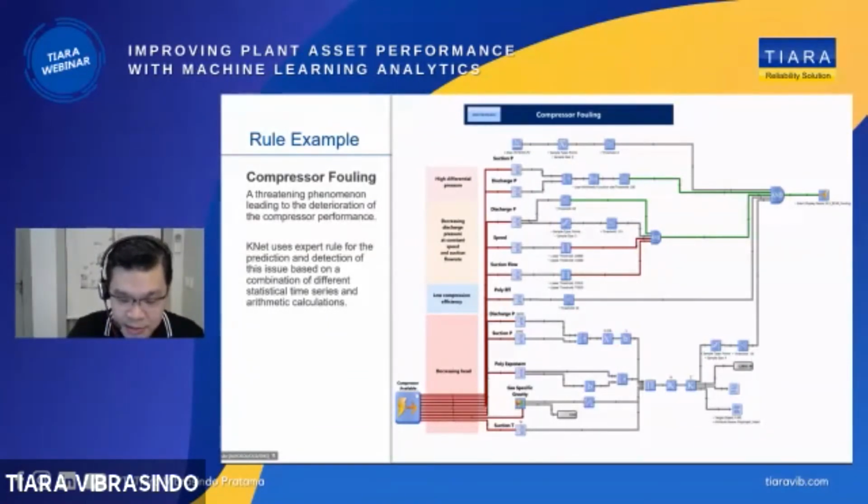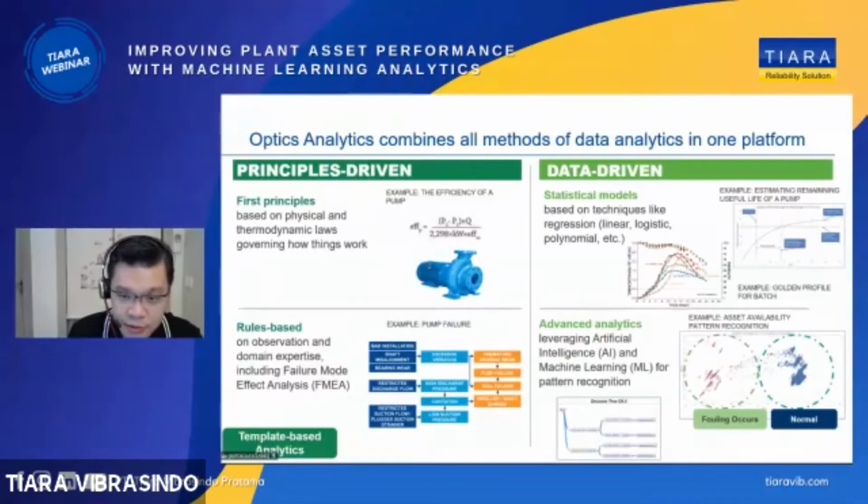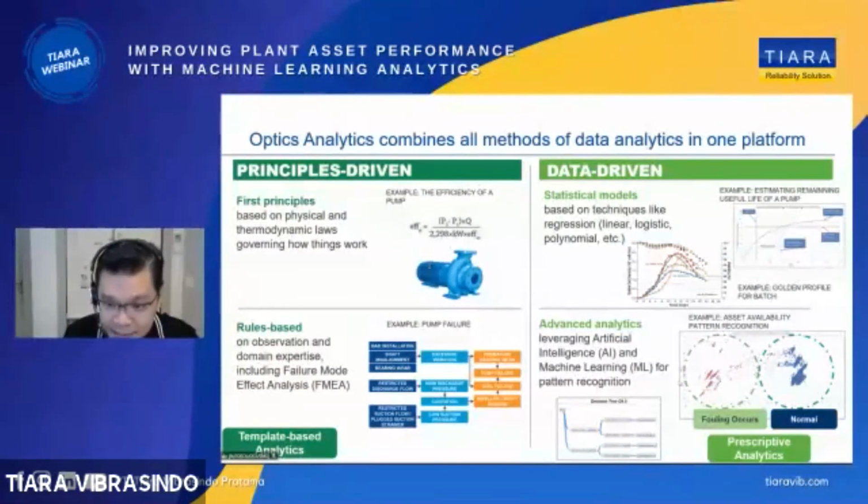Just to tell you from past experience, a lot of AI projects fail because the vendor says you need to use AI in order to detect or predict things. Wrong. This is a totally wrong concept. AI cannot predict everything. A lot of prediction can be achieved by simple formulas that figure out that a trend is moving up, or the rate of change is too much. That's why this software is so interesting. You must combine principle formulas, rules, statistics, plus machine learning, any methods that can help you detect and predict abnormality, and you must be able to apply them inside this automatic detection software.